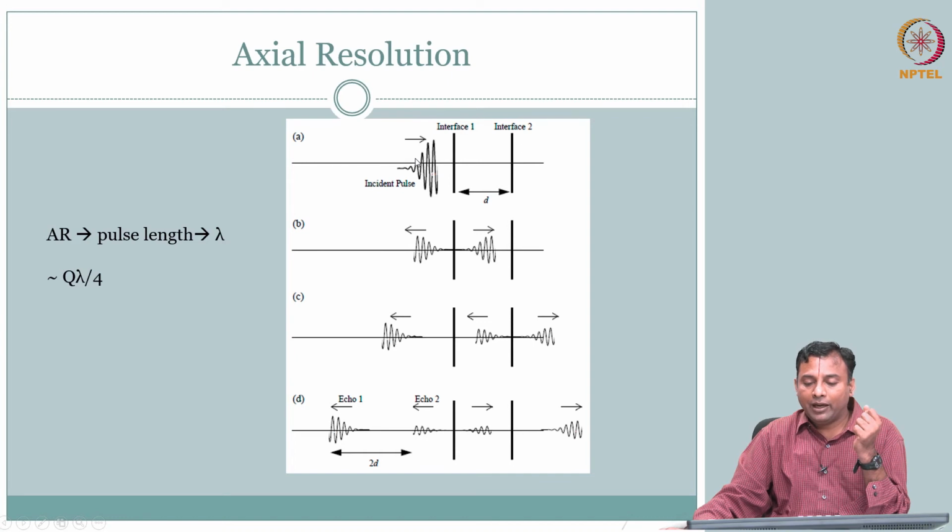So clearly you have this pulse, it is getting reflected, right. This is echo 1, it is getting reflected, this is your echo 2. Of course, echo 1 and echo 2 are separated in time because the interfaces are separated in distance, right. So if you do that, you are receiving this echo. So now your objective is, from this received echo waveform, which you get continuously with time, right, you have to say whether these two are coming from two different interfaces.